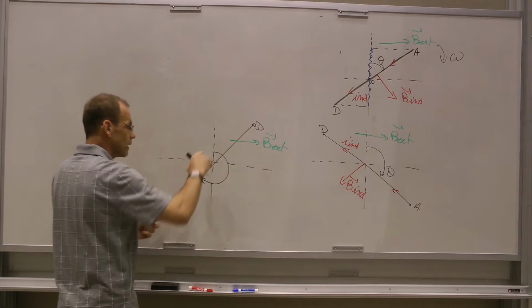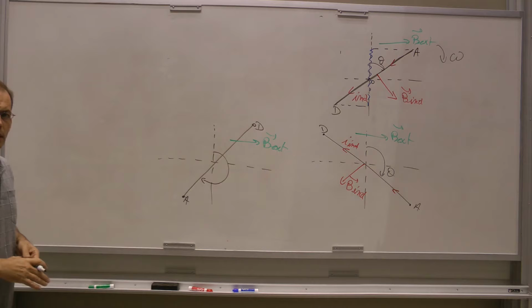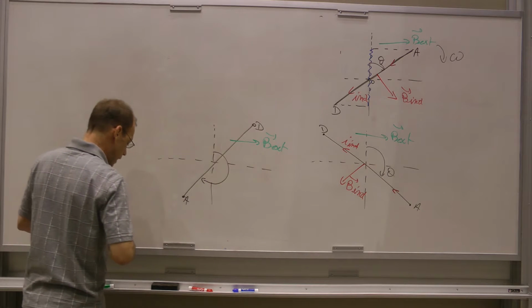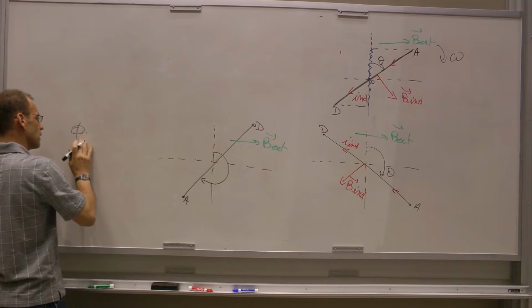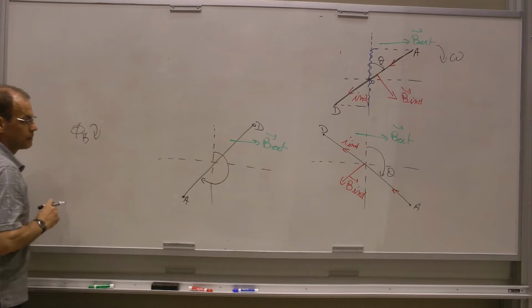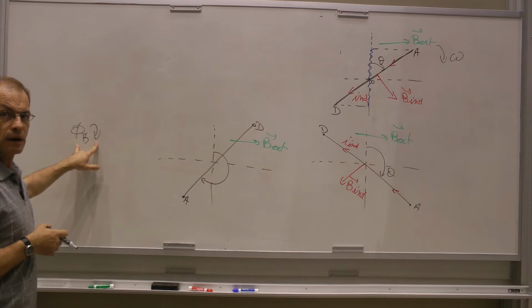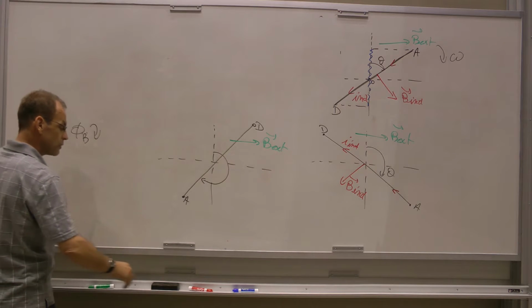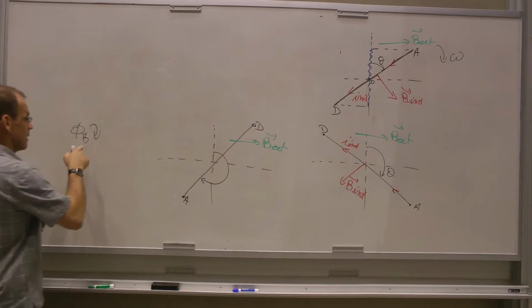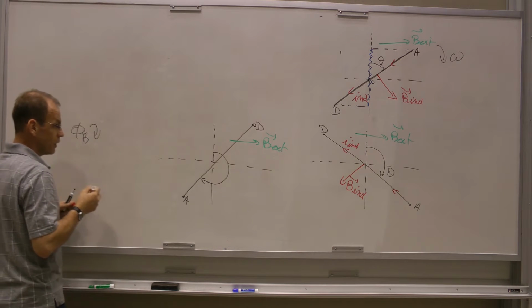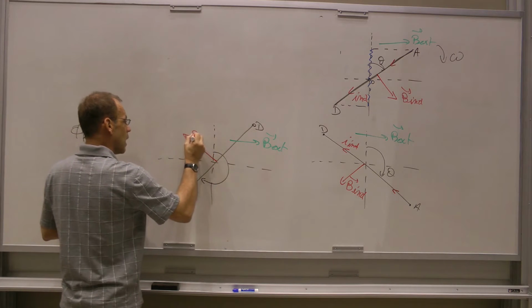Here's my angle theta, rotating this way. The loop sees less and less of the external magnetic field. That means the magnetic flux, phi B, is collapsing. Change in magnetic flux, Faraday tells us that there's induction phenomena. As there's induction phenomena, the circuit responds in a magnetic way in order to oppose the change in magnetic flux. The induced magnetic field has to be pointing opposite.